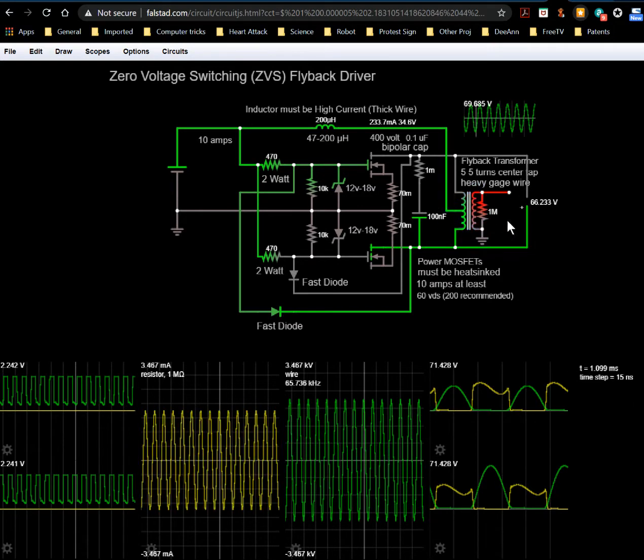In fact, if you ever take a plain Jane transformer, like a power transformer, and you take the primary and hook your multimeter up to it, in ohms, you can hook an ohmmeter up to it and take a potentiometer and put it on the secondary, short circuit the secondary with a potentiometer, so you can vary the resistance. You'll see that reflected in the primary. And if you put an inductance meter on the primary and a resistor on the secondary, believe it or not, you can control the inductance by varying the potentiometer.